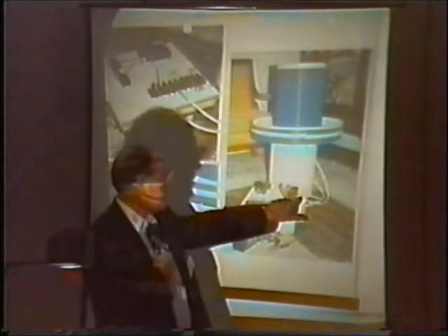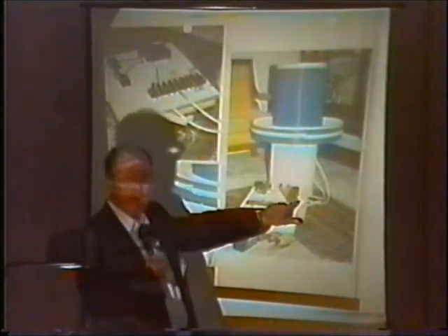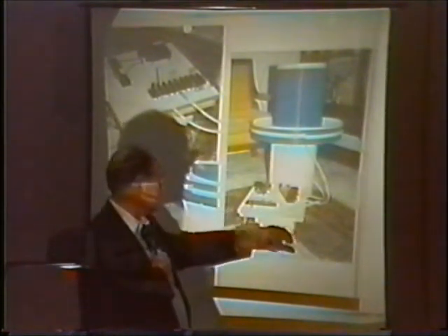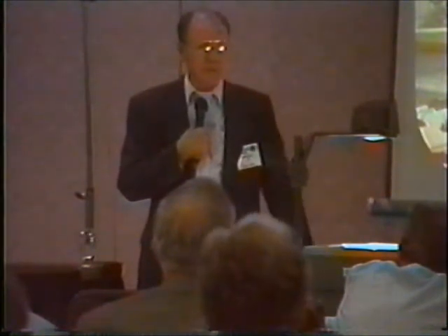It's working between the blue one here, which is the negative lead coming back from the L2 coil. The one that's white here is your positive lead going out. So between those two, you've got this 10,000 volt reconstituted mica capacitor. They take mica and break it up in little bitty pieces, and mix it into a glass ribbon type deal, and that becomes your dielectric in this particular case, and they go to very high voltages. I'm going to show you some in a little bit that go to over 250,000 volts.